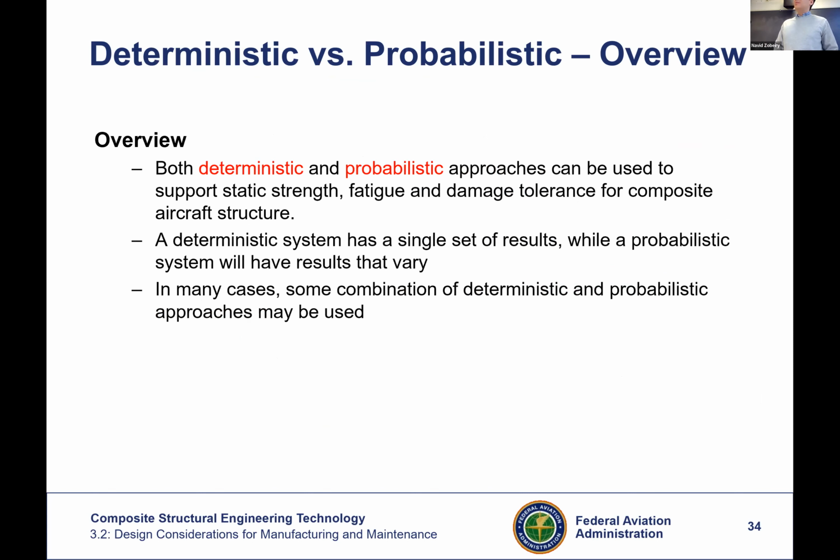So there is a deterministic approach and a probabilistic approach. The way this has been set is probabilistic. What do I mean? There was a study done by FAA and some other companies, and they gathered accident reports of all the impacts that have happened on a specific aircraft. I think there were 1,600 accidents that they had a report for. They gathered how much load was applied in that impact. You can see the number of accidents and then the impact energy.